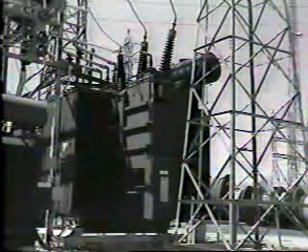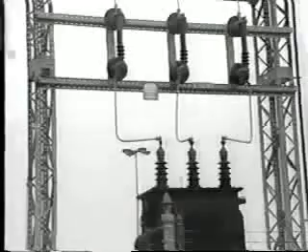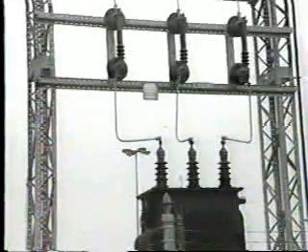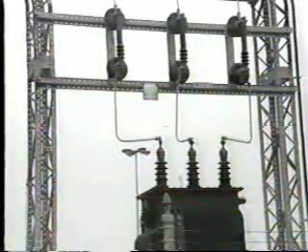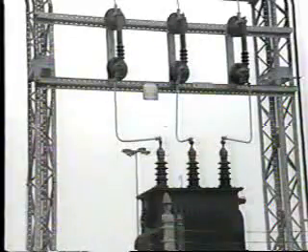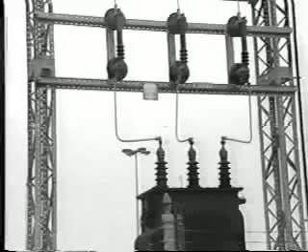The type of protection scheme used depends to a great degree upon the size and importance of the transformer in the power system. But another factor is the installation itself. Sometimes, in order to economize, the transformer is not provided with circuit breakers, hence the protection equipment must be designed with this in mind.